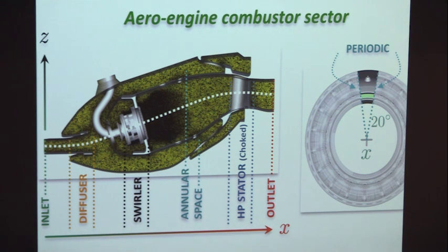You cannot cool this thing with water. Every time you look at this picture, I see the piston engines people laughing and say, hey, you just put liquid cooling. You cannot do that in something which flies, okay? It's just, the weight would be too much. You can do that in a car. So you have to find a way to cool these walls with what you have. What do you have? You only have air, cold, what we say cold, 700 K air.